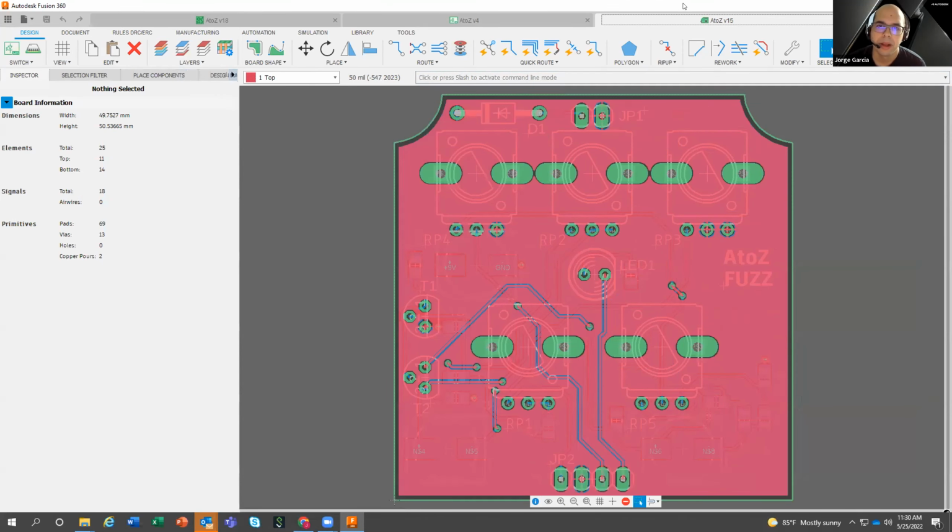Okay. So one thing that maybe wasn't noticed is when you open an electronics design, even if it has a 3D model associated to it, by default, it won't open it right off the bat. The reason for this is opening up a 3D model takes a lot longer than opening up just a schematic and board. And you don't need to have the 3D model open to keep forward and backward annotation working. So you can just open the 3D model whenever you need it.